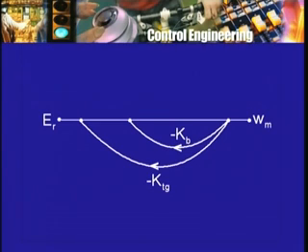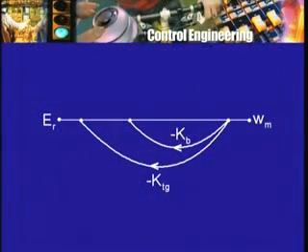K tachogenerator omega m is an actual physical signal. Kb omega m is not an actual physical signal that is measured and then connected to some device whatsoever. So our system still has only one real feedback loop, although on the block diagram or on the signal flow graph two loops do appear. Therefore you might think of feedback being used in two places, but of these one place is just the action of the motor itself. That is the way the DC motor runs.